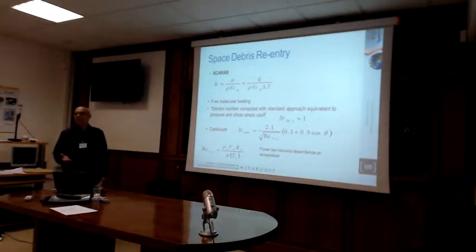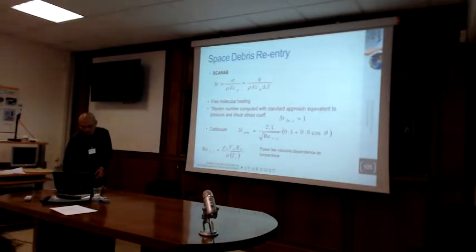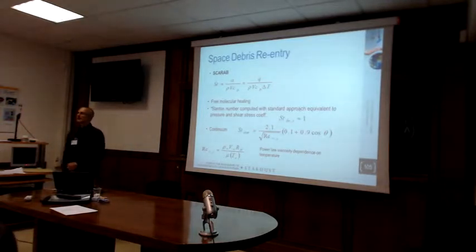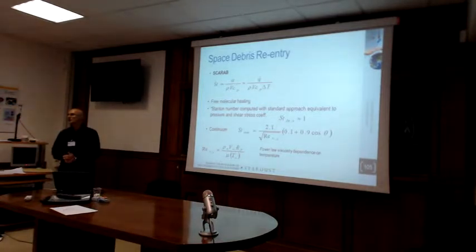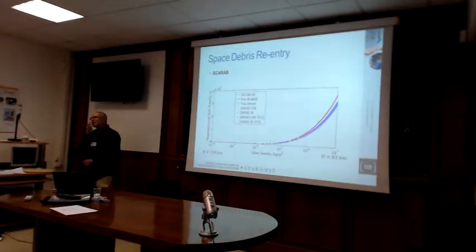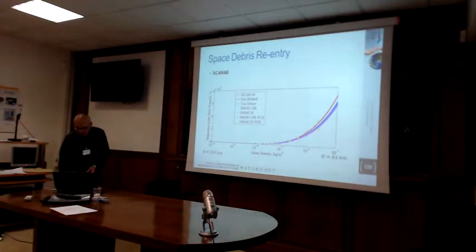which is another dimensionless number considered in aerodynamics, a ratio between the density, the velocity, the radius at the nose, and the dynamic viscosity of the fluid, considering the stagnation temperature, because they also implement a viscosity law as a function of the local temperature. This is something that will be presented in more detail by Piyush, because he is working on this to make our own tool.